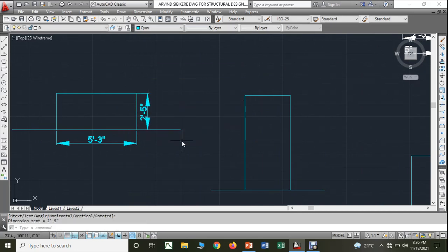Now when I write b d cubed by 12, definitely the b value is higher, and the depth is considered thrice, that is cubed. So here the depth value is much lower than the breadth value, therefore the value of I will be lesser. But if I take this,